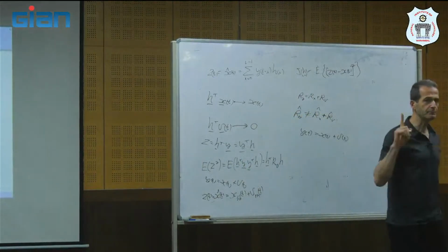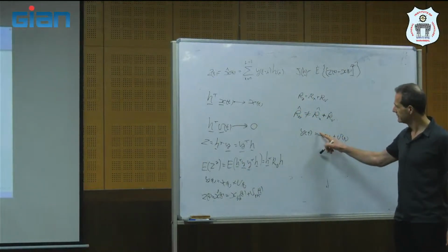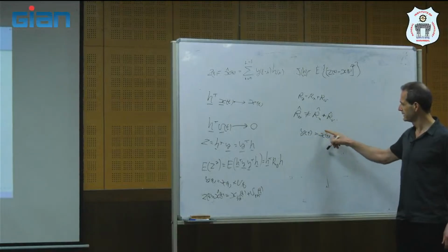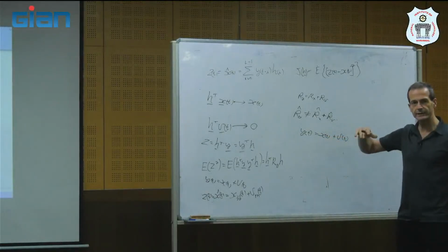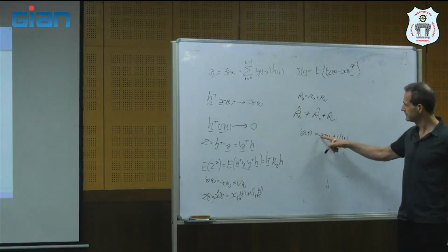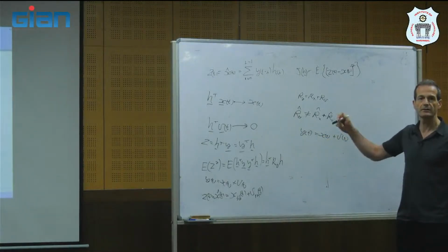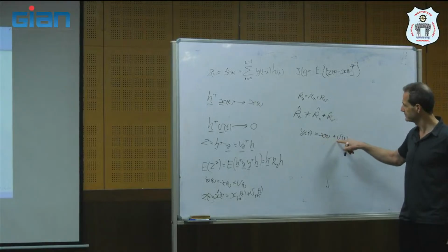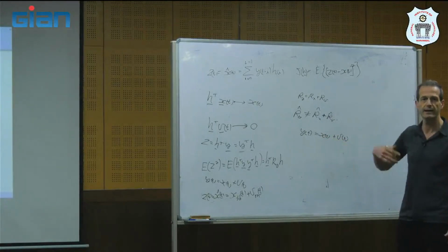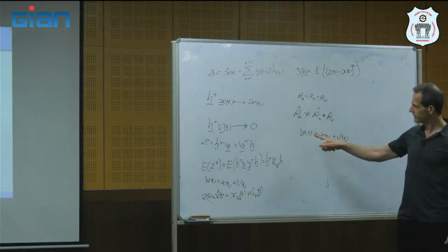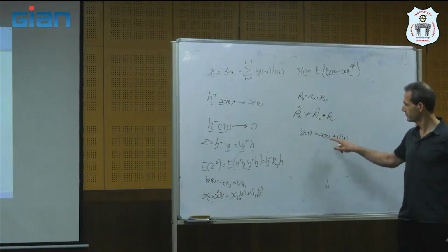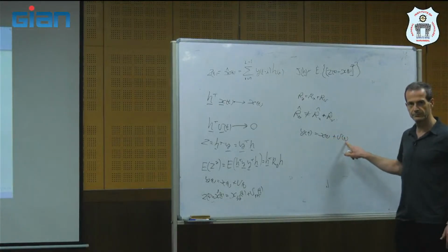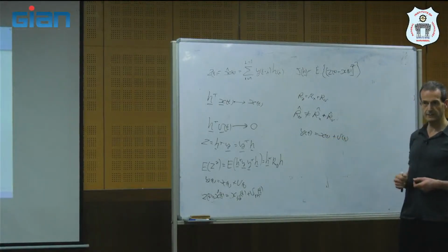So high input SNR means that this variance of X is much larger than that of V. So the more we increase the SNR, it means that this ratio, the variance of X divided by the variance of V, is higher. So the correlation between Y and V will be higher or lower if we increase this ratio? Lower, okay?